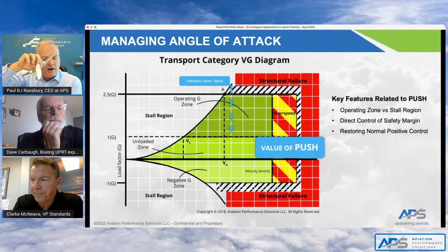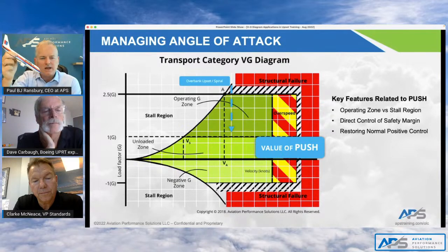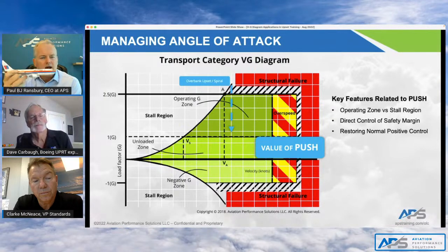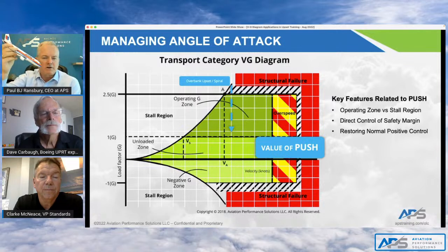And remember, because of what Dave talked about earlier, unloading is going to optimize your roll rate to get those wings back underneath you quickly. Because if you're successful by unloading and rolling properly, you're going to minimize your airspeed gain. You're going to minimize your dive angle, all of which count towards minimizing your turn radius, which is altitude loss. And of course, managing energy based on where you are in relation to maneuvering speed is critical in this.